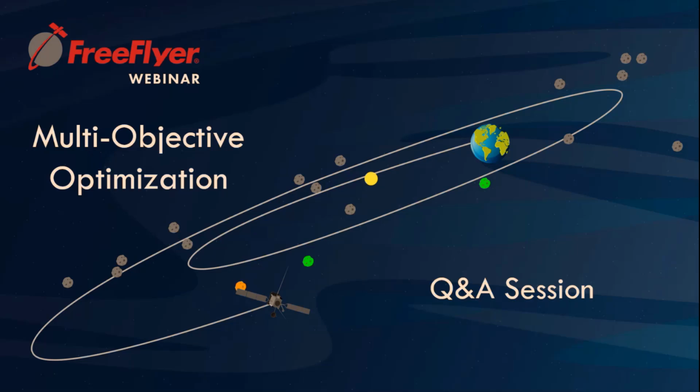If you have hard constraints, or if you have one objective that you know for certain is more important to you than the other objectives, you can use sorting functionalities to sort the Pareto front according to one objective first, and then according to another objective second, and so on for the objectives you have, in order to create a list that has your preferred or most desired solution at the very top of it.